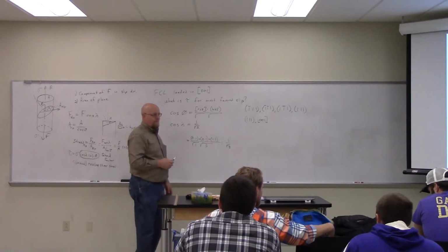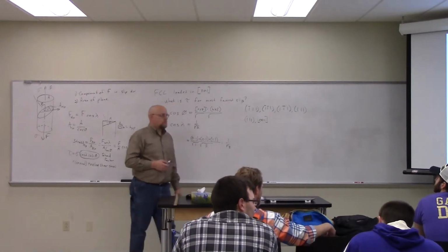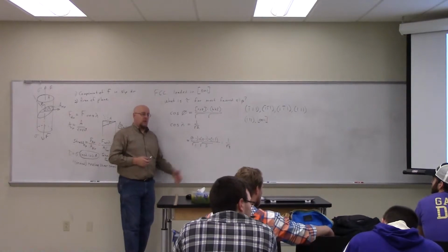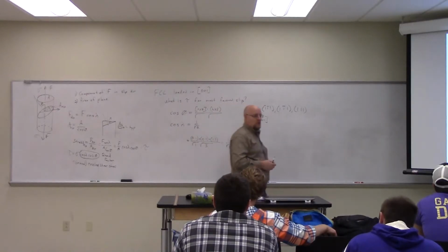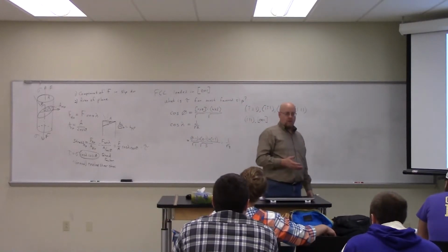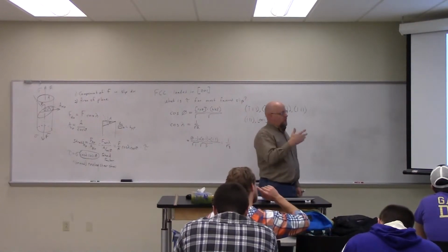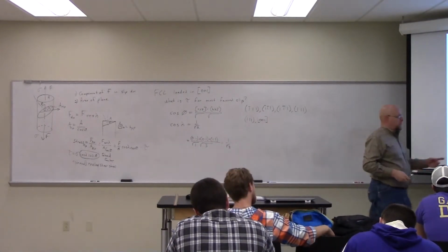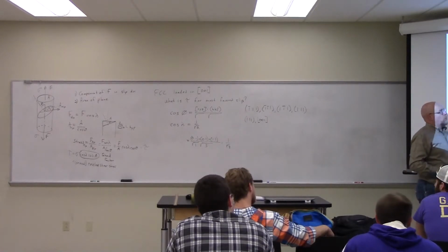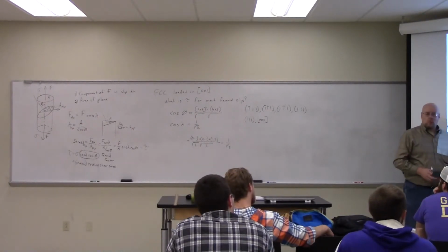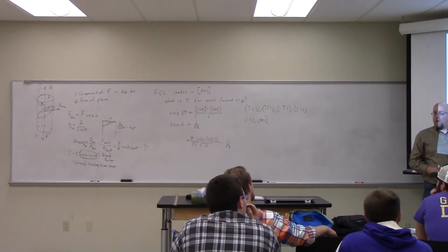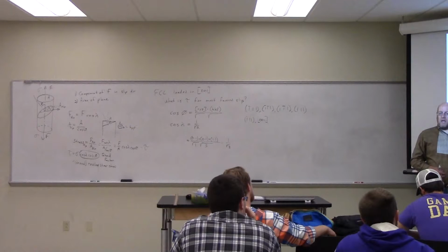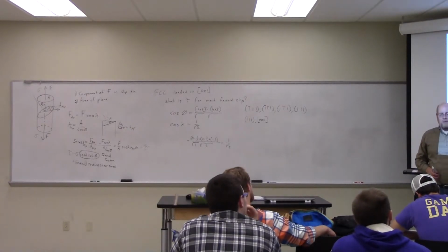So it didn't matter which plane you chose or which direction you chose. In this case, they will all be 1 over square root of 3. Now, if I had pulled it in the 1, 1, 1 direction, let's go back to this back corner. Let's use their nomenclature because it makes it easier to see. This is the 1, 1, 1 plane. Where's the 1, 1, 1 direction? It's perpendicular to it. It's going from this corner to that one, the body diagonal. What's phi going to be for that plane?